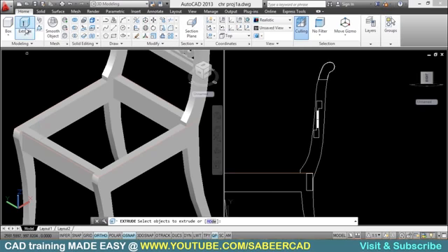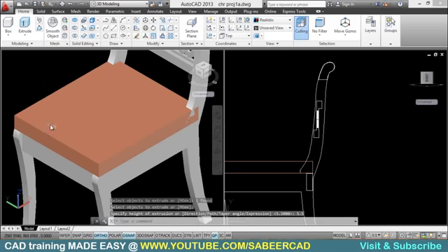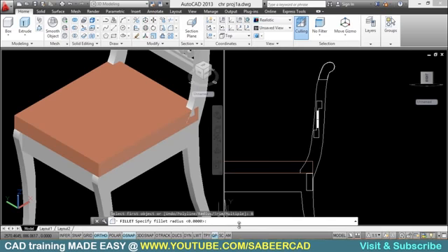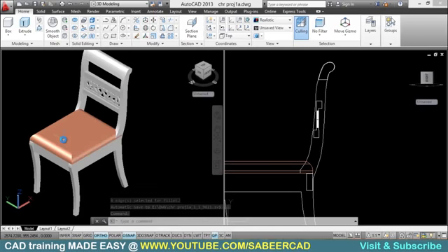Now you can just extrude this profile using the extrude command. Select it and you give the height of extrusion as 5.5 centimeters. So I'll type the value 5.5. Now you can just fillet all the corners using the fillet command. So I'll click on fillet. When I'm asked to specify the fillet radius, you can just go to radius and you give a value of 4.5. Okay, now you select this edge. Then it'll ask you for a radius once again. Just give an enter to accept the existing radius. Pick this edge, and select all the rest of the edges to complete the fillet.